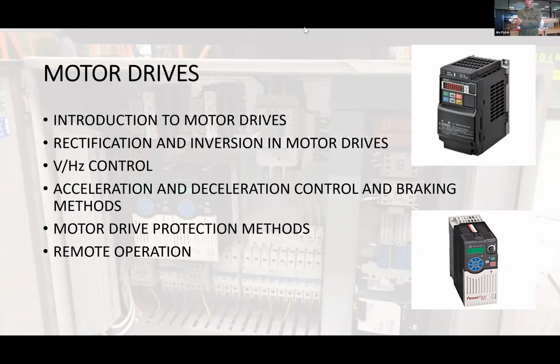And last but not least, I think one of the biggest things for a student to understand is direct versus remote operation. Up to this point, they have been operating the motor drive on its face panel. Now we're going to take these inputs, for example, a remote speed potentiometer, a start and a stop button, a jog button, and we can do several labs at once with a motor drive.